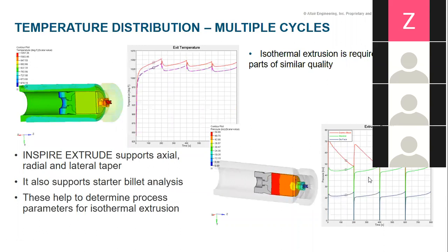And in this one, you can check the exit pressure and pressure contours. On the left hand side, it shows the pressure of your exit finished component, and on the right hand side, it shows how much pressure is being applied by the piston to the metal to get extruded. So basically this is a very main factor we have to consider. Because of this factor, we need to assign the machine, how much machine tonnage is required to extrude the particular component.